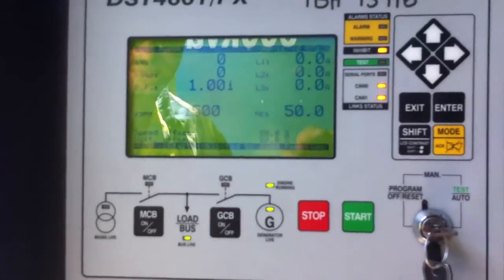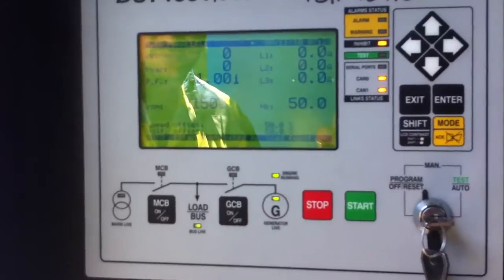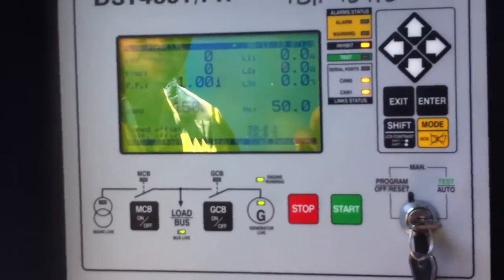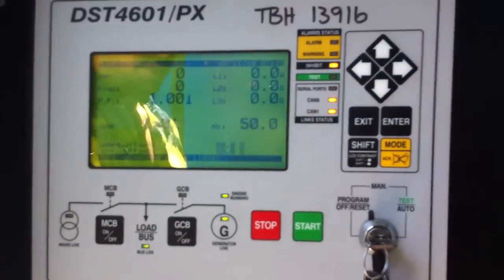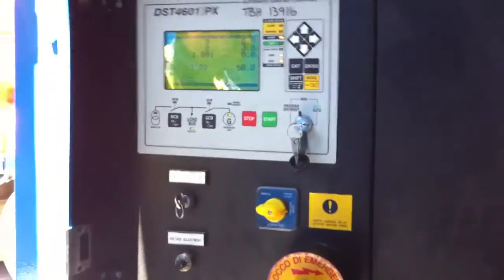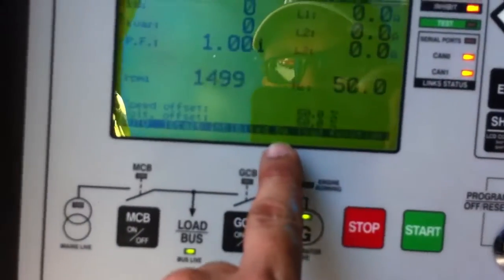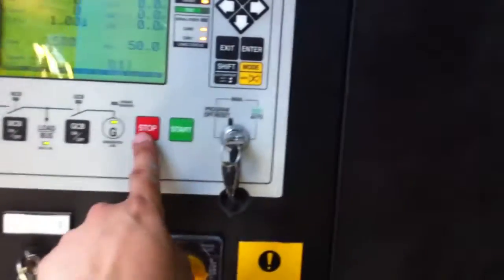So we're just waiting for it. Circuit breaker off. Cooling cycle now. So the generator is now shutting down because there is no load. And number one generator will take the load of what is on. Until we hit 12.5% of the output of the generator, the second generator will not activate. Okay, now we're going to wait for this generator to shut down, which at the moment is 93 seconds for cooling off. So what we might do is just stop it.